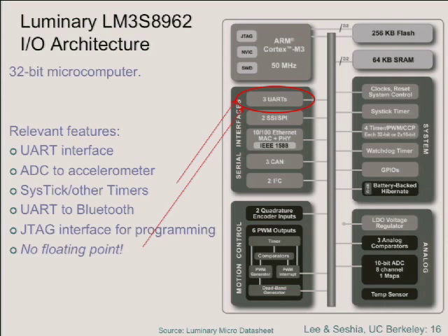If you assert 32 values on 32 wires, at the receiving end you want to latch those at just the right time that you see exactly the same 32 values. Well, what if the propagation delay on this wire is a little bit slower than the propagation delay on that wire? Then you have to slow down the rate at which you latch these things enough to compensate for that.